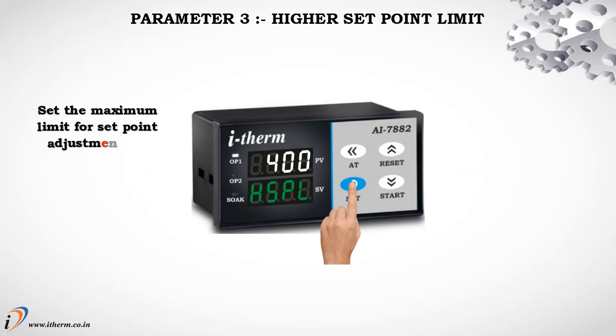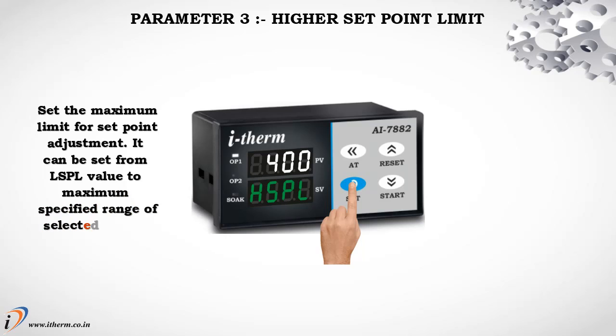Parameter 3, Higher set point limit. Set the maximum limit for set point adjustment. It can be set from the LSPL value to the maximum specified range of the selected sensor. The default HSPL value is 400.